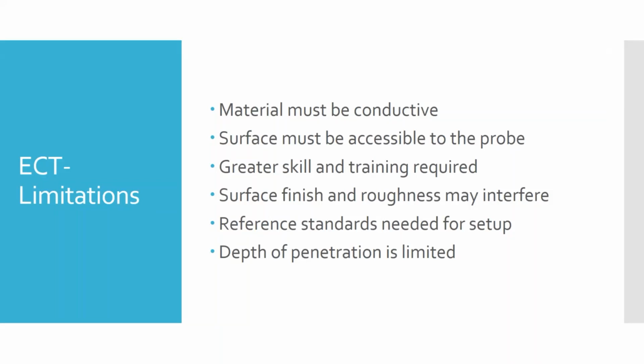But for eddy current testing, we have to have a reference standard that in some way simulates or matches the type of flaw we're looking for in the given material. And that reference standard has to be fairly similarly constructed to the part we're looking at.